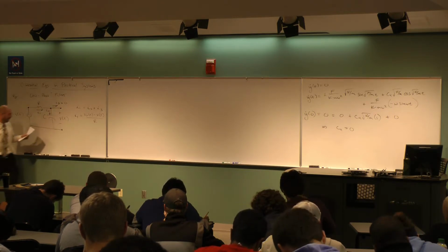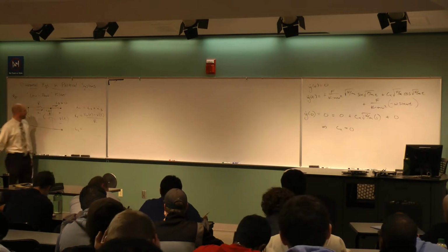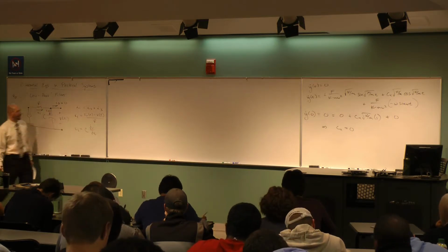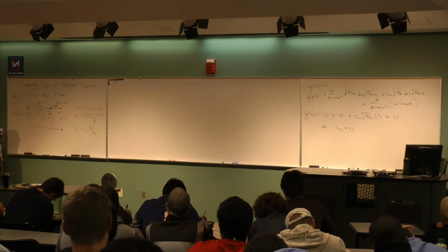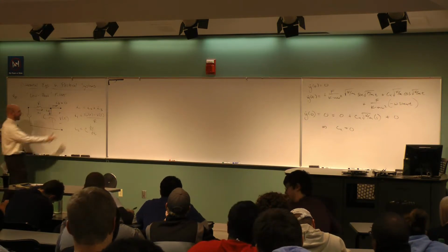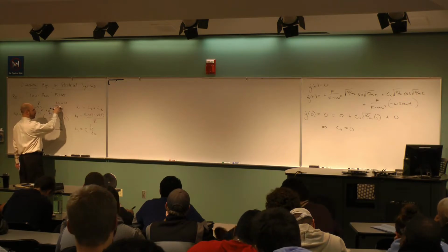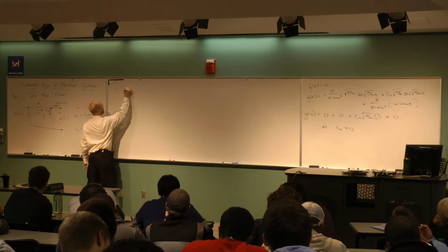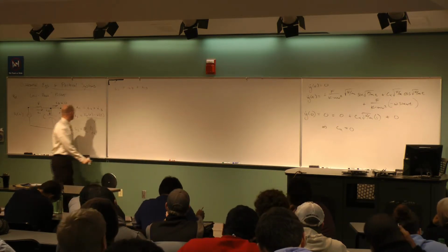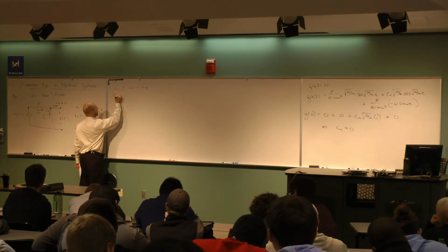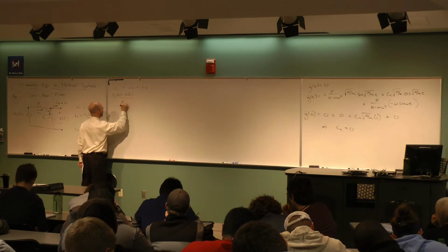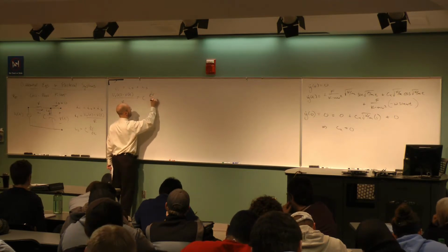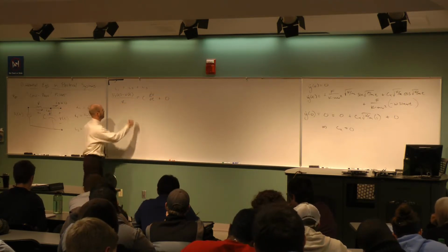And then finally, the I2, we know from our derivative relationship, is equal to C times dV/dt. That's the way that capacitors work. So that's it. I know what the values are here. I've got I1, I2, and I3 is equal to 0. I should be able to plug that all in. I1 is equal to I2 plus I3. Let's just plug in the numbers. Vs of t minus V of t, all over R, that's I1. That's equal to I2, which is C dV/dt, plus I3, which we said had to be 0.